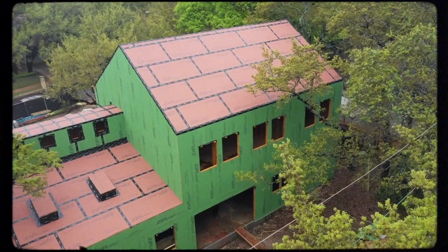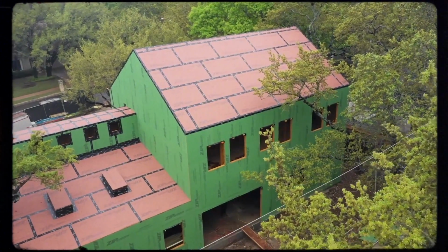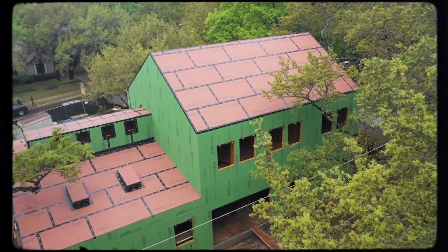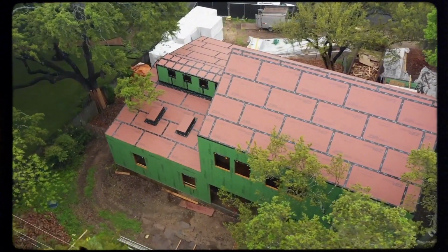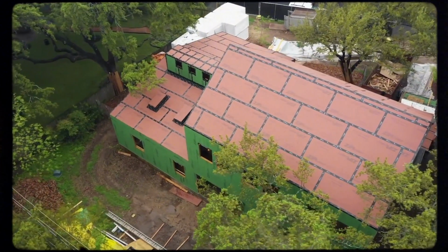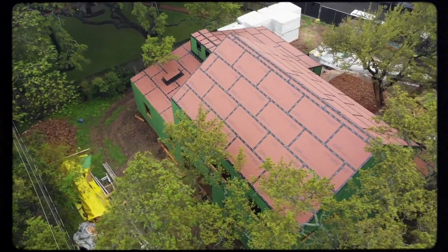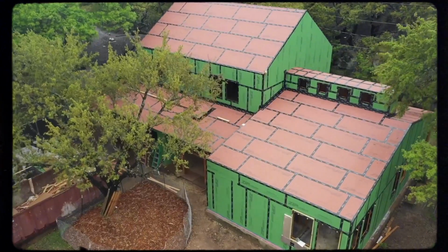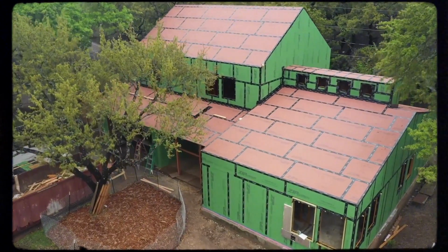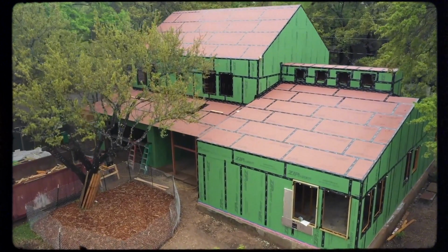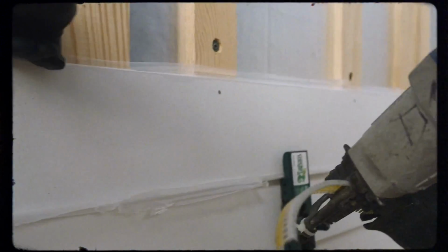That's your house wrap, that's your ZIP System sheathing, that's whatever you're using on top of your wood structure. If you think about our buildings in North America, they're generally wood-structured buildings with some type of control layers. And we're talking specifically about the water management layer today. And then on top of that is a cladding. That cladding is going to let some amount of water through it.